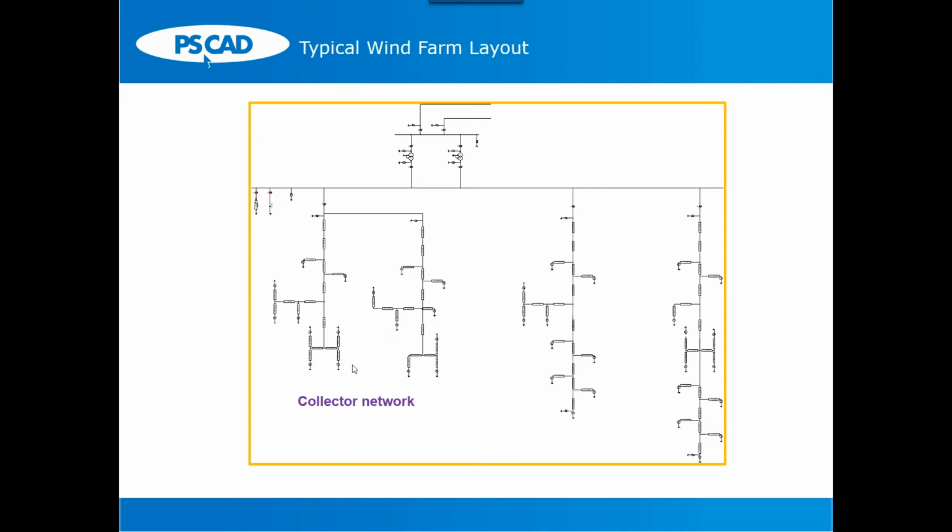So if you include 9 wind turbine models in a single PSCAD simulation, it will be very slow. So for that reason, now you can use the parallel network interface facility or capability of PSCAD, where you place different wind turbines in different PSCAD modules running on different computer cores, processors.